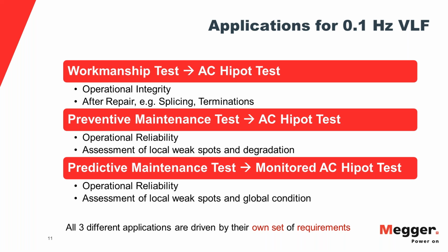And then you're doing the fully standard compliant VLF, and you add a condition assessment, like a trend indicator, of which there are 3: leakage current, partial discharge, and tan delta. And then depending on which stage of the cable's life you are in, not all of them make sense. Like for instance, during acceptance testing, tan delta is absolutely useless and nonsense. You even get incorrect readings.